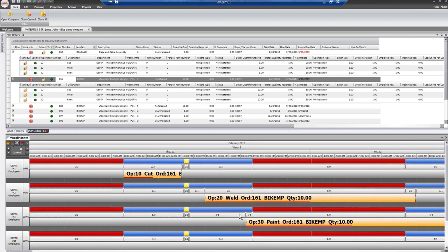Now, if you were using our iLink labor product, the web-based labor reporting, production reporting solution, you could actually report the quantity completed on these operational steps, and Visual Planner would pick that data up and show you on these operations the quantity reported by this red line. If you hover over it, it'll tell you how much you've already reported, and also in the task panel above.